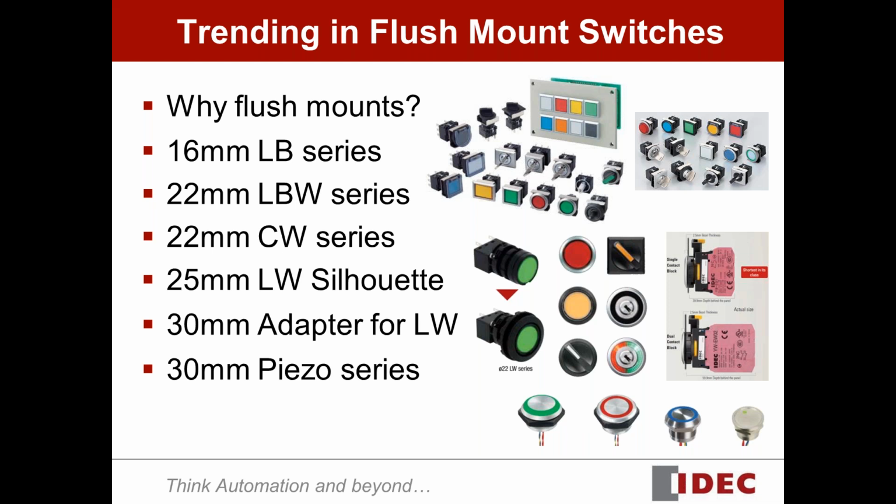So controls really start to fall into low voltage controls, and that gives us the opportunity to use light duty switches, lower the cost, use less panel space, and still be enough to do all the controls necessary, and also make the panels much better organized and more appealing in appearance. So this is a trend that's coming. We also see it starting to pick up in the US.